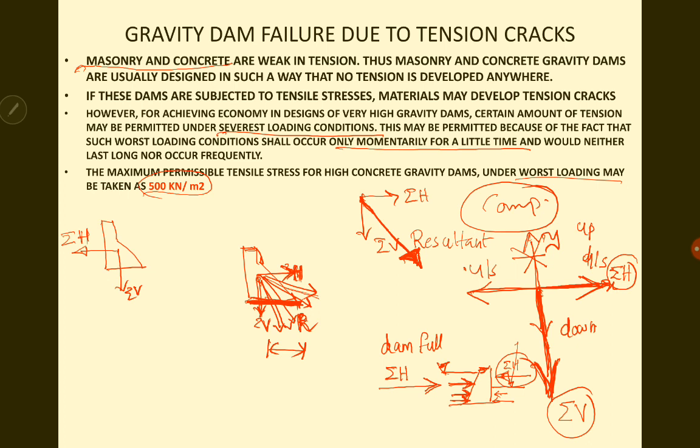The resultant will now change its direction. The resultant will be somewhere here, whereas in the previous case it was near the toe. Now the resultant has moved towards the heel of the dam.